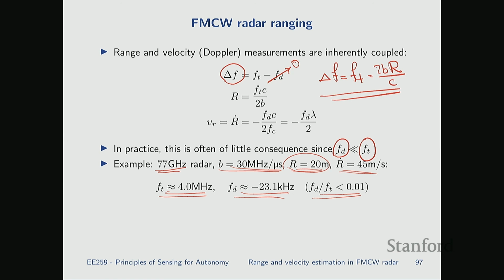In the case of sonar, we know it's inherently suited for applications where things are not moving fast because it's a slow sensor. When you plug in the typical numbers for sonar, you would see that the Doppler shifts are sub-kilohertz. They're so low that it's not even worth mentioning. We didn't even bother with it for sonar.